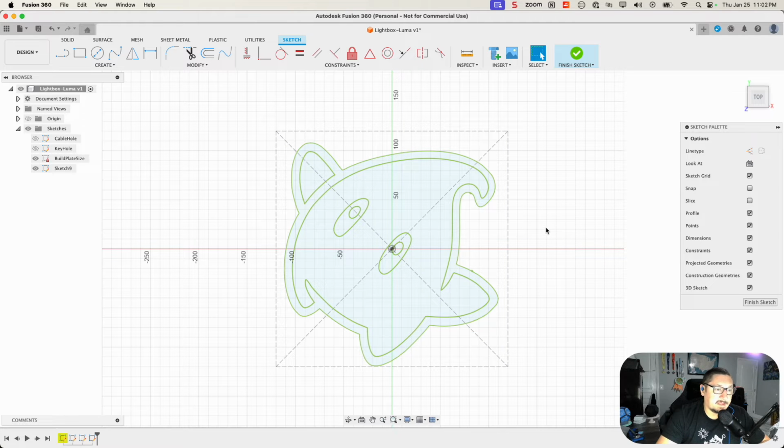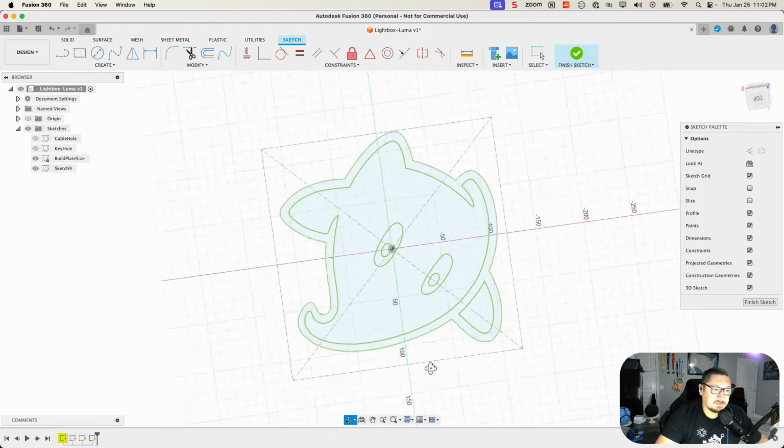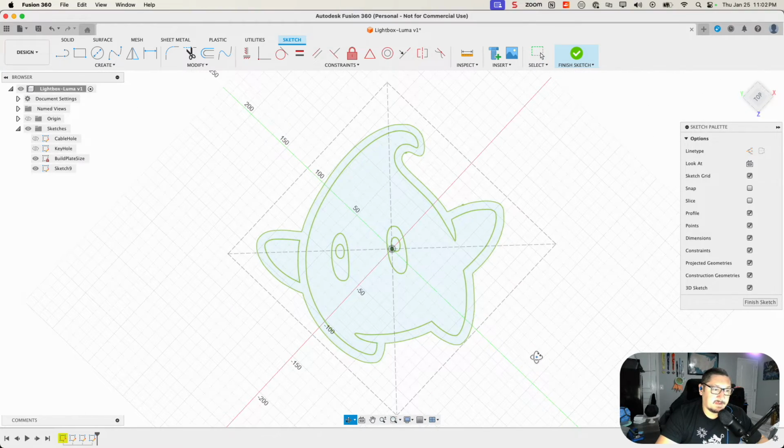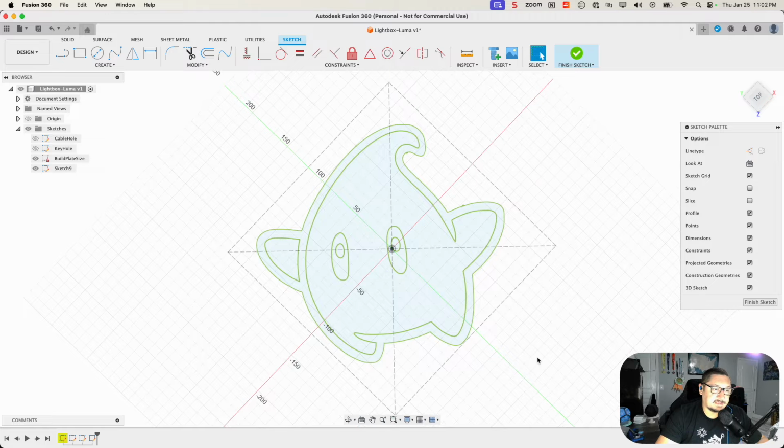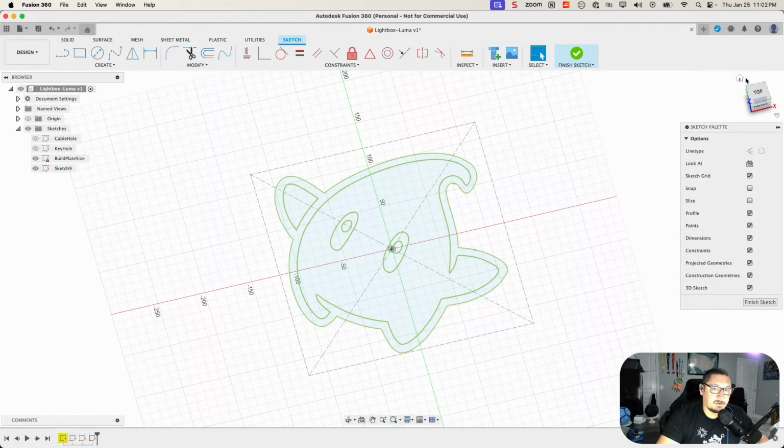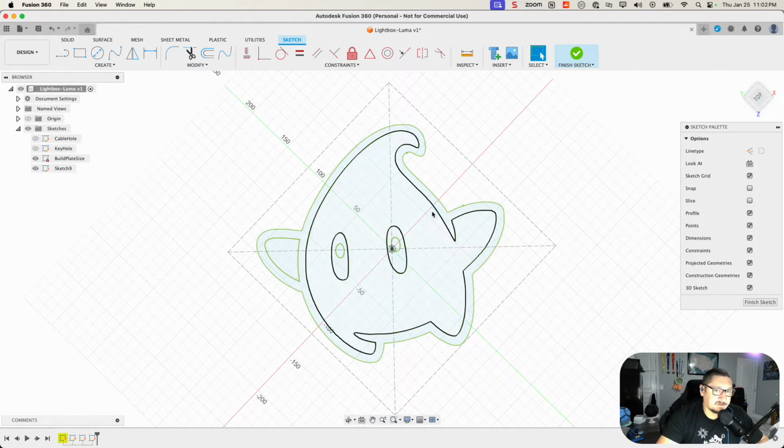One thing we'll note is that it's a little disorienting like this, so you can use the orbit tool to basically rotate this guy the right way forward. Once you have that, you can just come up to the top little cube here, right click it, and then set current view as home, fit to view, whatever you want to do. And now anytime you're looking at it, you can always come back to that home view, so it's all nice and straight for you. So you only really need to do that when you're slanting your image to fit it a little bit nicer, but it's one of the nice things to use.